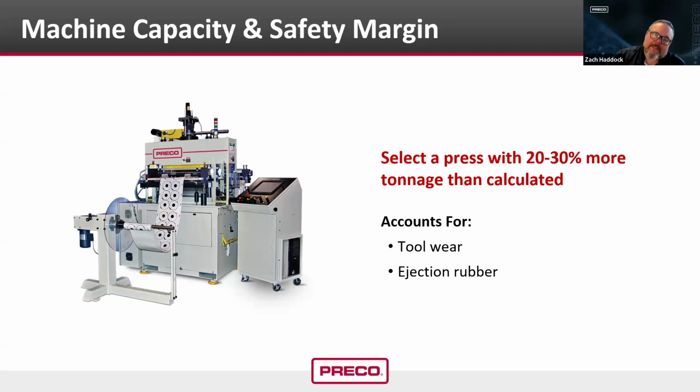So as you can see, it's really simple to calculate tonnage. There are some real advantages in throughput, your ability to do delicate processes. The other side of it is one of the bonus sides makes the press cycle quieter too. And in the instance of, say, a male-female die, you can actually switch the press to run off position, and it will automatically run on minimum tonnage for you. And in that instance, your throughput goes through the roof.